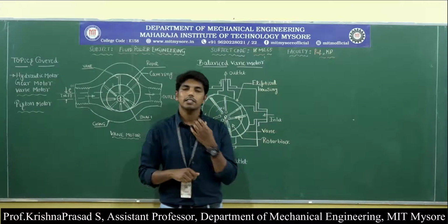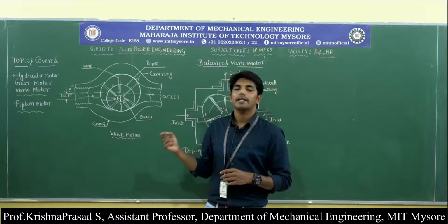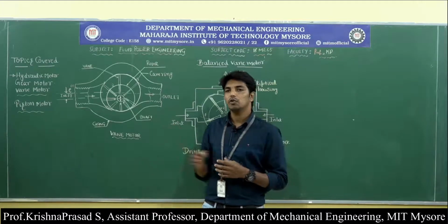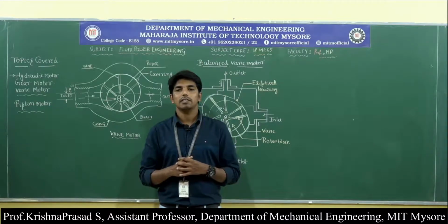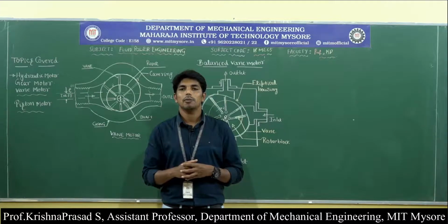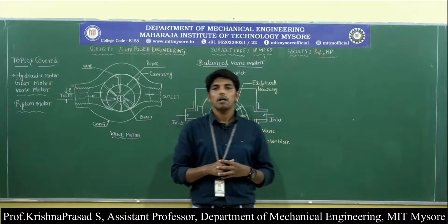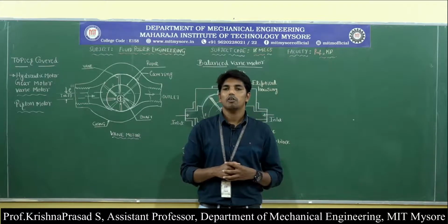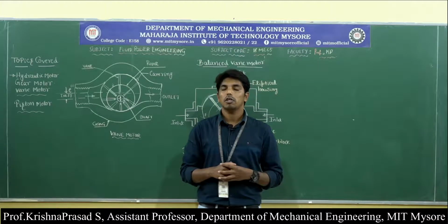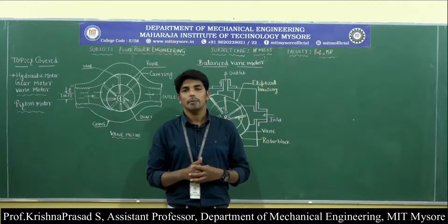In today's class, we are discussing the hydraulic motor, types of hydraulic motor, construction and their working. First we need to know the definition of a hydraulic motor. Hydraulic motors are mechanical devices which convert hydraulic energy into mechanical energy in the form of continuous rotation as well as torque. The construction of the hydraulic motor resembles the construction of the hydraulic pump. In a hydraulic motor, the pressure of the oil pushes the freely moving element, thereby developing continuous rotation as well as torque.